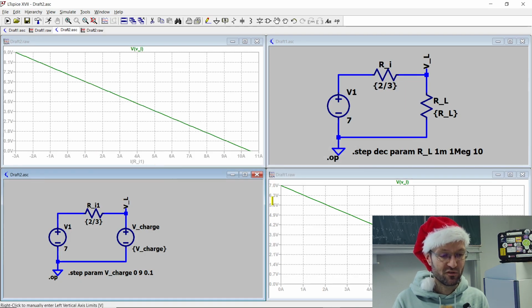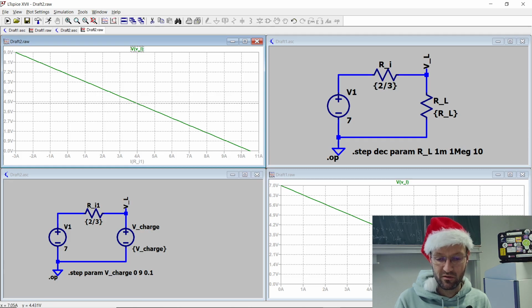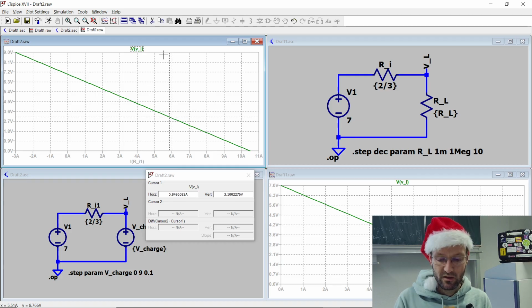Of course, the curves look pretty similar, but here we now have, this would be our y-axis, or this would be the voltage axis, and now we go to the negative side and we have this 9 volt, minus 3 ampere, 0 volt. Yeah, I can also put a marker on here. The marker window is unfortunately always hidden behind my camera window. And we can move the marker up and down with the arrow keys on the keyboard. So we start with 9 volt, minus 3 ampere.